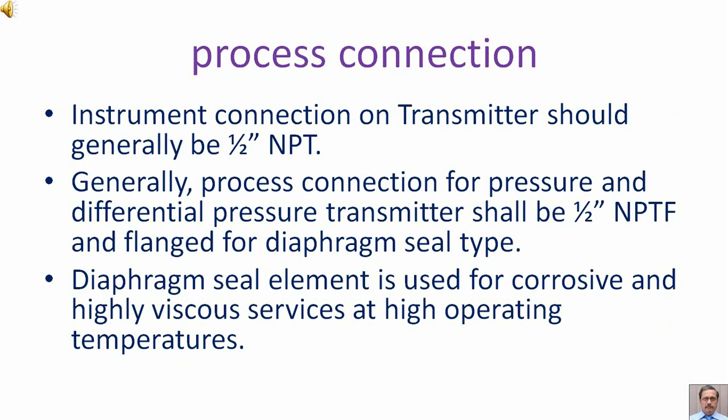Instrument connection on transmitters should generally be half-inch NPT. Generally, process connection for pressure and differential pressure transmitter shall be half-inch NPTF and flanged for diaphragm seal type.